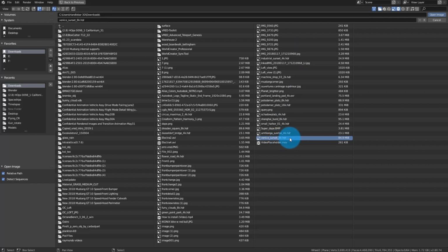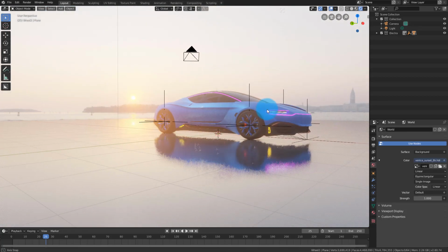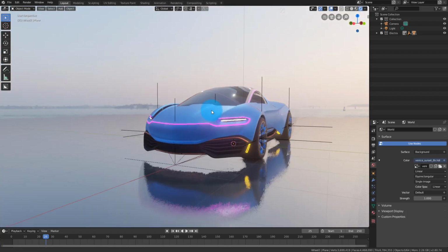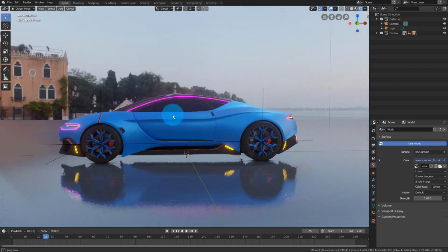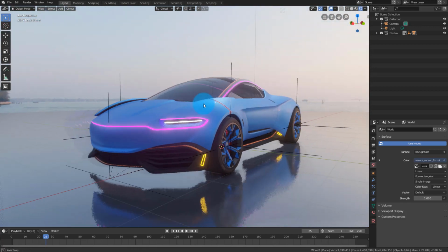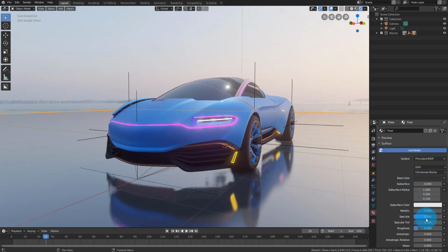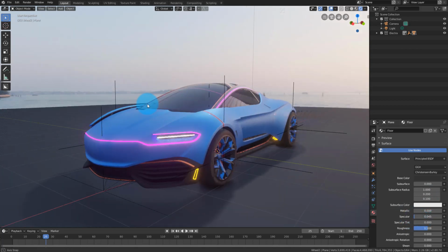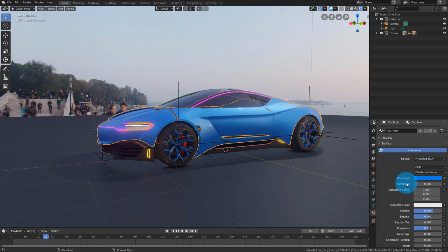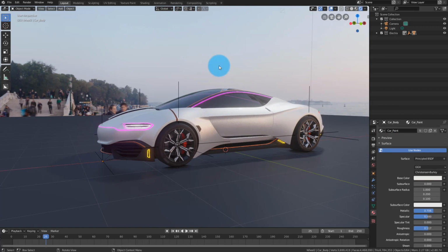And once it loads, we're gonna have a good idea of how our final scene is gonna look in terms of lighting, because now that you choose an HDRI, that's when you really can start tweaking all the different materials that you made for the scene. So right off the bat, for me, this really reflective floor is a bit distracting. So what I'm gonna do is turn the roughness up, and I'm gonna turn the specularity down. The next thing I'm gonna do is change it from a blue to a white, just to mimic the initial video I made.